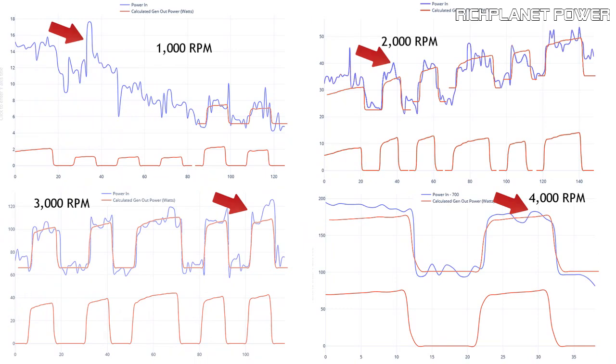Now, by doing this overhaul, I resolved a problem that I hadn't realized was there. The steel housing, which carries the rotor brushes, that's this thing here, had been scraping slightly against this copper shaft, which was contributing to the unstable power readings that I showed earlier. Now, once the shaft was assembled with this problem resolved, the machine ran smoother with a much more steady input